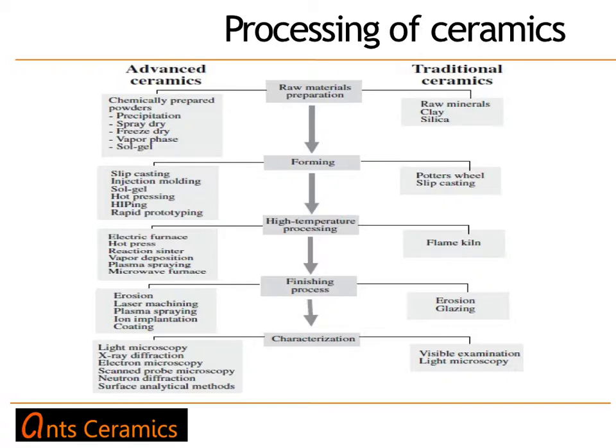These are fired generally in controlled atmospheres, in a process controlled electric furnace or microwave furnace, or hot pressed, and machined, ground or lapped using laser machining, plasma machining, and ion implantation. Different characterization techniques are followed, like light optical microscopy, XRD, AFM, and different surface analytical methods to analyze advanced ceramic components.